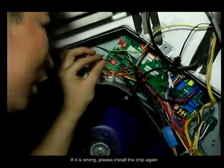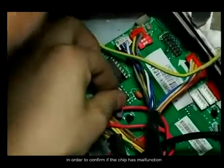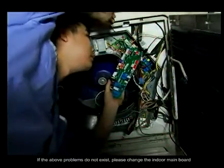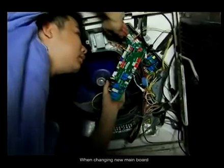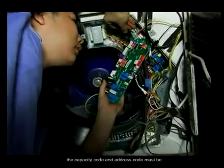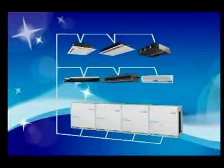If it is wrong, please install the chip again, or replace the chip of the malfunction unit with the same model chip in order to confirm if the chip has malfunction. If the above problems do not exist, please change the indoor main board. When changing new main board, the capacity code and address code must be the same as the main board with malfunction.